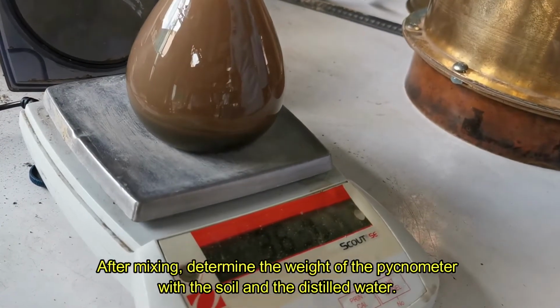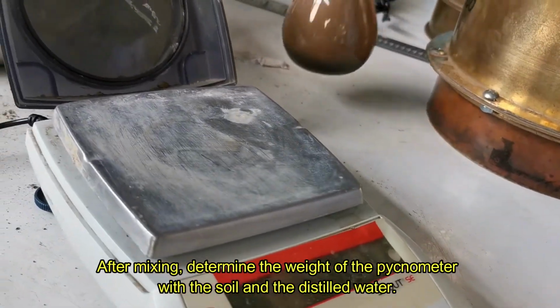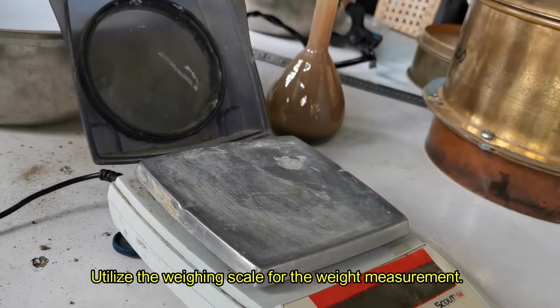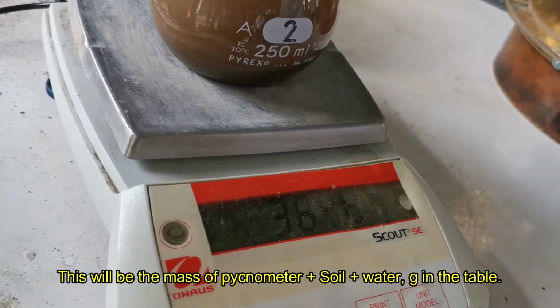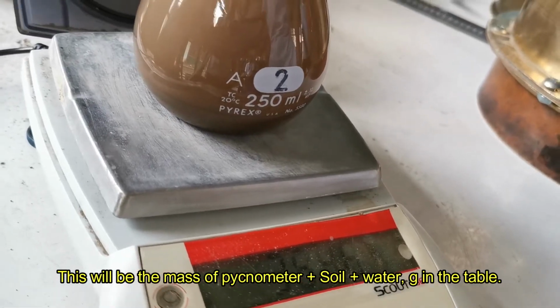After mixing, determine the weight of the pycnometer with the soil and the distilled water. Utilize the weighing scale for the weight measurement. This will be the mass of pycnometer plus soil plus water, in grams, in the table.